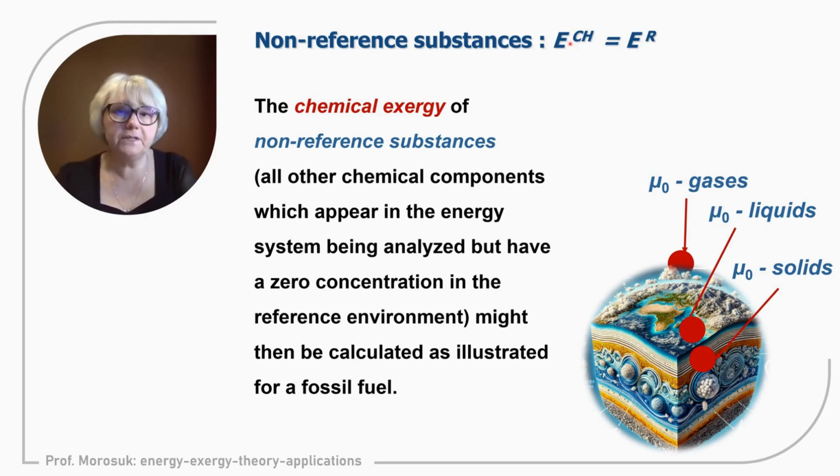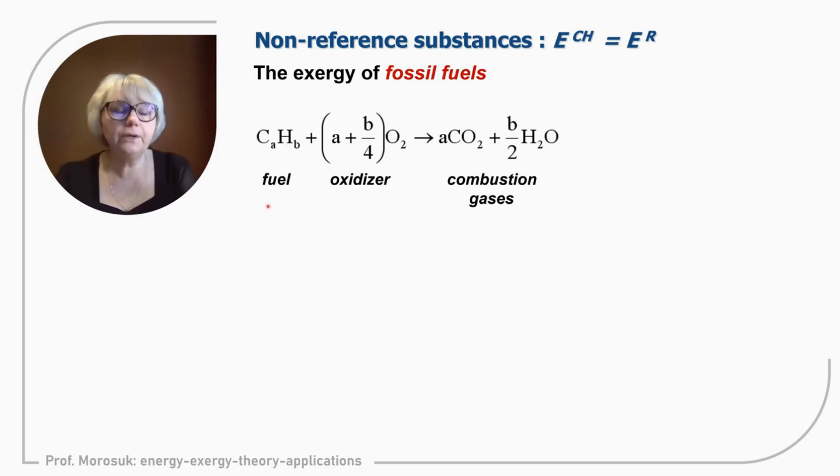And how to proceed with the reaction part, we will illustrate with the help of fossil fuels, because chemical exergy for fossil fuels is also not standard chemical exergy. We need to calculate this value ourselves. So let us assume that we have a hydrocarbon as a fuel, and we would like to calculate chemical exergy. In order to calculate chemical exergy of any fossil fuel, not only a saturated hydrocarbon as a gas, we need to write a chemical equation for the combustion process.